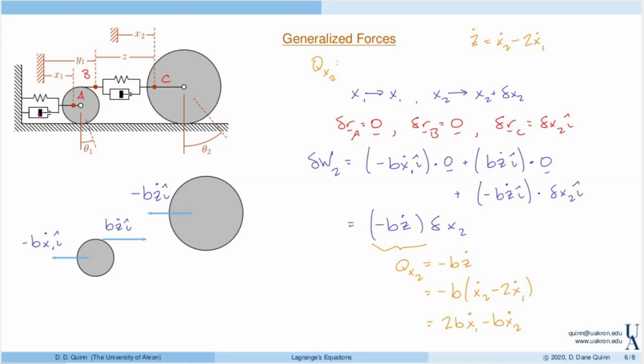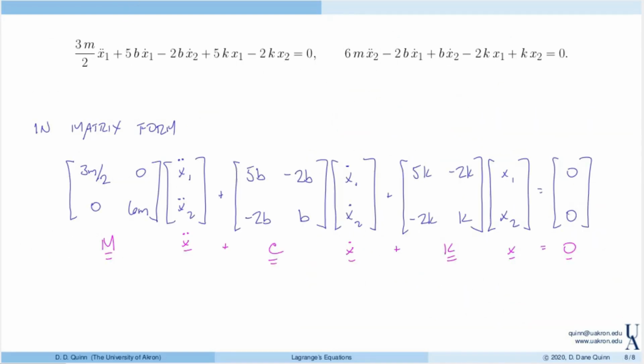I have stiffness and damping, and they always appear together, and in particular with the same values, or at least the same ratios between stiffness and damping. So in this specific example, the damping and stiffness matrices look similar. But again, in general, that's not true. So I just want to point that out in this problem.